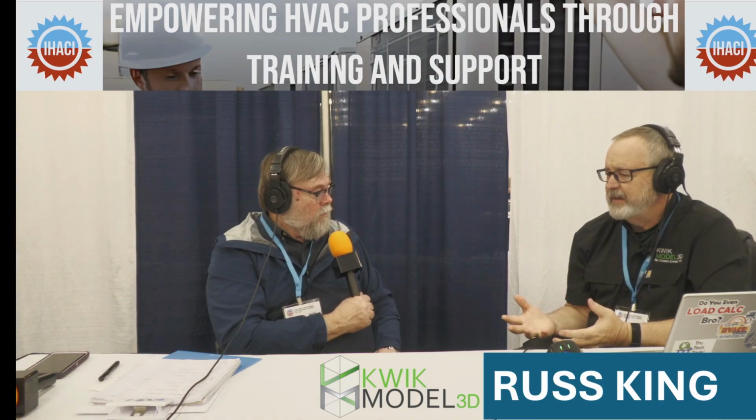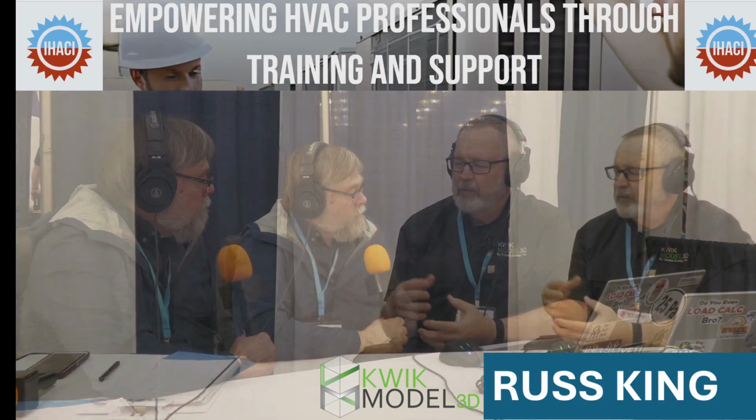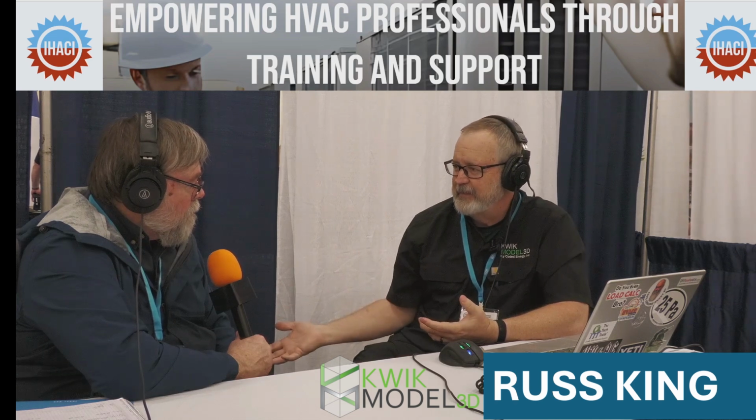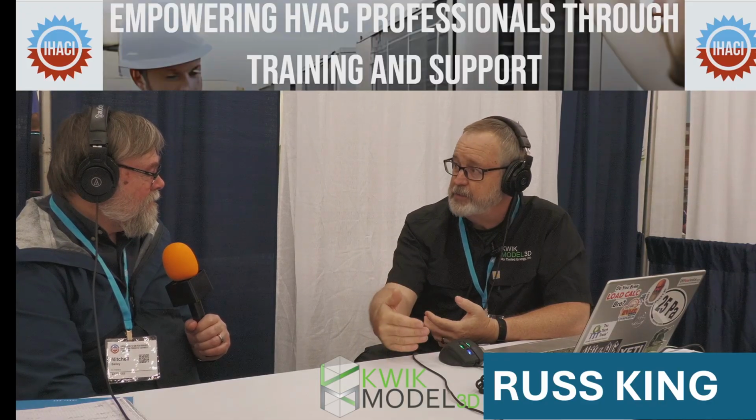Absolutely. So I teach a lot of classes, and one of the things I say is don't design a system for a crappy house. Don't size the equipment because the house is leaky. That's like putting a bigger engine on your car because it has flat tires. No, you fix the tires first. You fix the house first. Make the house reasonable. If you're not sure what features are in a house, I tell people to assume the features are what they should be and what they could be. Don't assume that they're bad. That's enabling poor construction, in my opinion. I agree with you 100%.